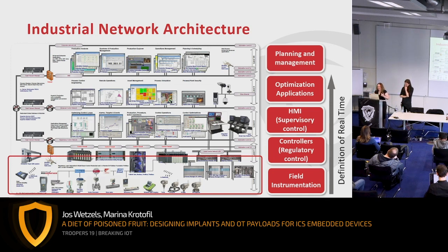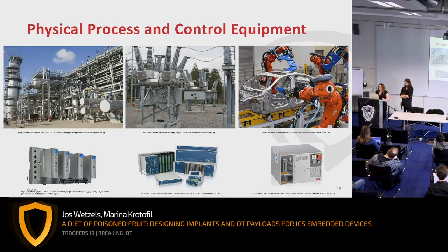have a meaningful impact. Because if I try to do something from the HMI or from the optimization application, the controllers which sit at the bottom will, in between my operations, which is 1 to 3 minutes, try to bring the process back into the normal state. So it's very difficult to win at the upper layer. If you really want to cause a very meaningful impact, you have to be somewhere close to the process. So basically, you have to be on the controllers.